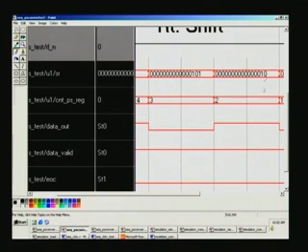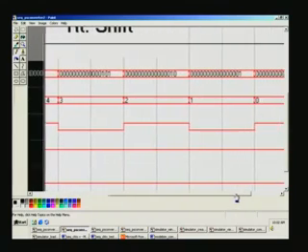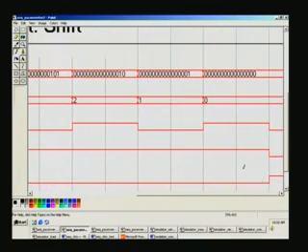So 1 0 here, and you can see that data out is going alternately low and high, and all through data valid is high, and end of conversion is 0 because all the bits are not serialized. Coming to the end, 1 0 1, then 1 0 is in the shift register, and then comes 1 because 0 gets dropped, and finally 1 also gets dropped.